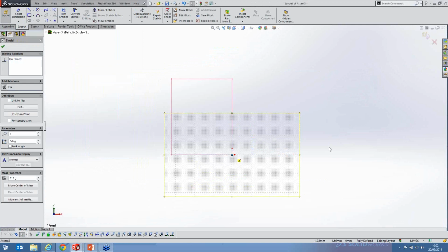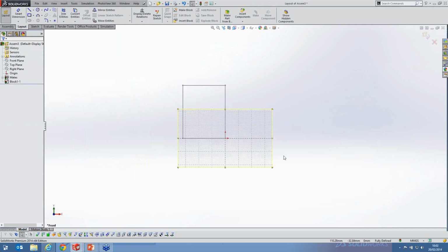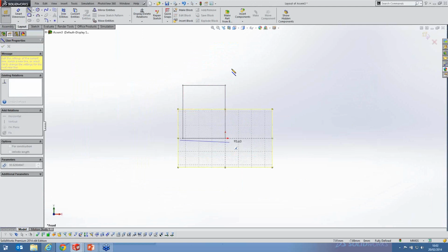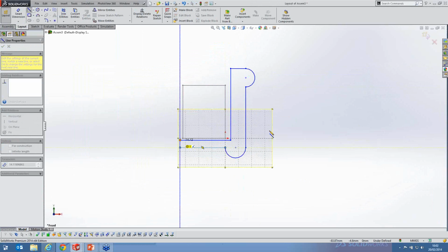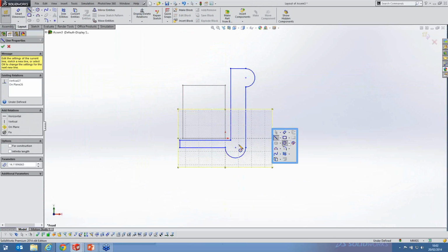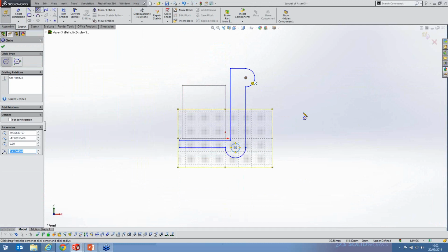I'm just going to place that down and make that horizontal there. We want to make a mechanism for the tines to lift up here. So the next thing I want to do is draw very quickly some pivot points that we're going to use. We can do this using the sketch tools in SolidWorks nice and quickly. You'll see that I can translate to an arc quite simply and then go back to a line. So I've created some pivot points there. We'll stick some circles down just to indicate what they are.